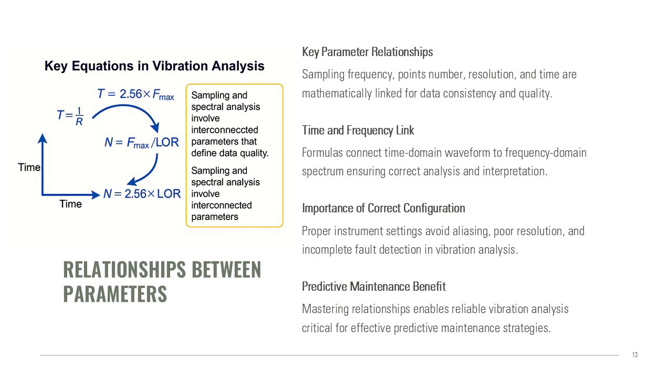Misconfigured settings can lead to poor resolution, aliasing, or incomplete fault detection. Therefore, mastering these concepts is essential for reliable vibration analysis and predictive maintenance.